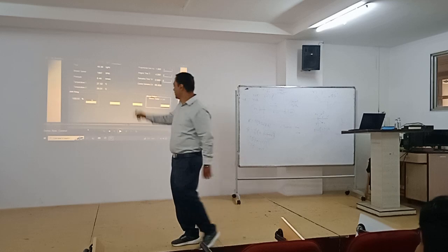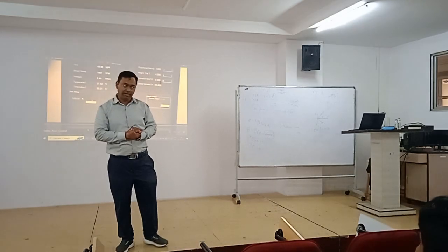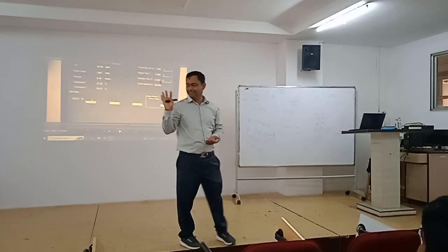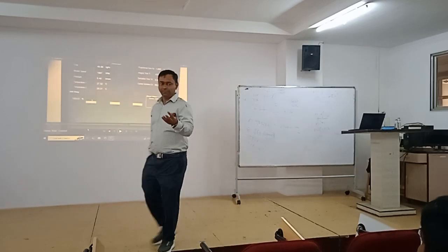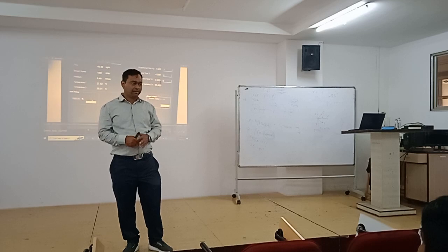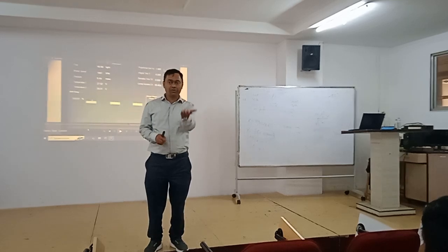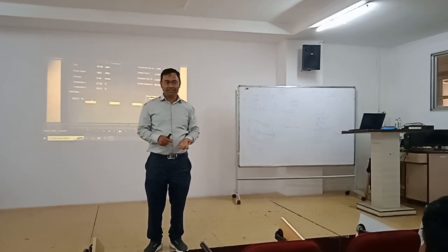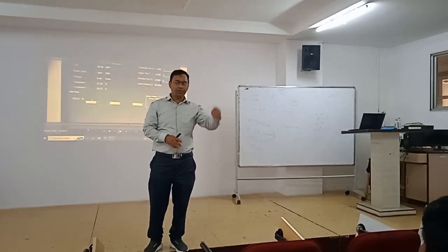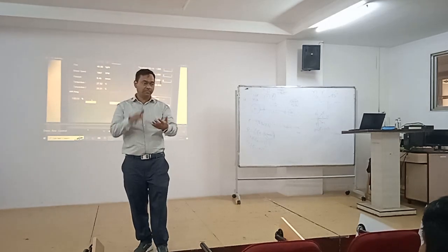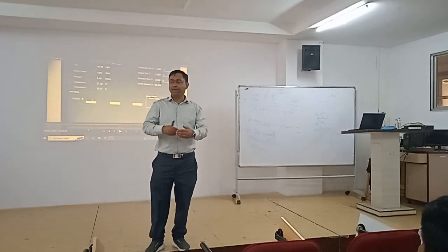See, typically what happened? Earlier we were working at normal temperature. Now we are increasing the temperature of the air. Correct? So now, when you increase the temperature of the air, the air is going to be lighter. So since air is going to be lighter, your actual mass flow is going to decrease. But the system is working in closed loop. It tries to maintain the actual mass flow. It should be the same as your desired mass flow. So how will it maintain that?